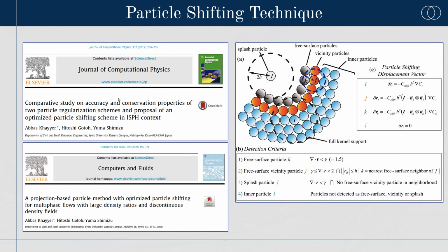A first important aspect arises when considering free surface flows. In order to satisfy the kinematic boundary condition at the free surface, the shifting velocity must be modified. In particular, it can only have a tangential component along the free surface, as emphasized by Dr. Caillère and co-authors.